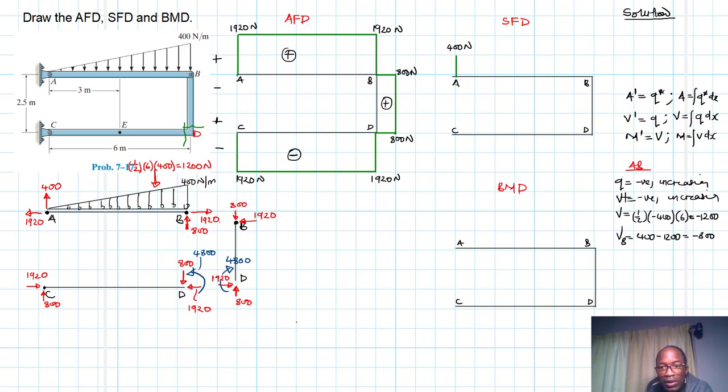All right, and our load is being governed by a polynomial of degree 1. That's a linear function, polynomial of degree 1. Therefore our shear will be governed by a polynomial of degree 2, which is going to be a quadratic function. Great. The slope is negative and increasing. Therefore I will not show you two slopes to choose from. I've done that in the previous video. Just go directly. So the slope that is negative and increasing, it will start from there.